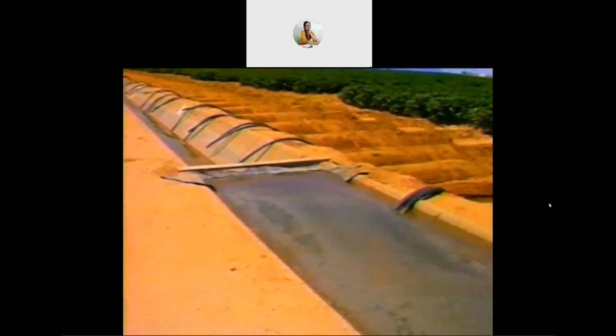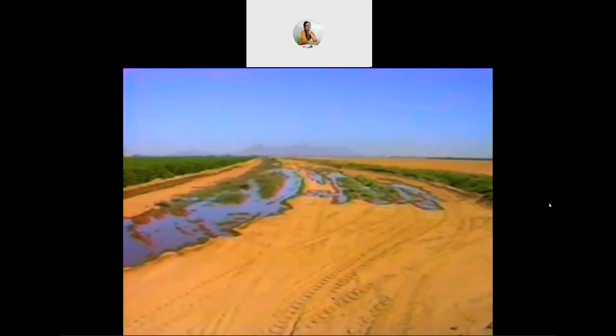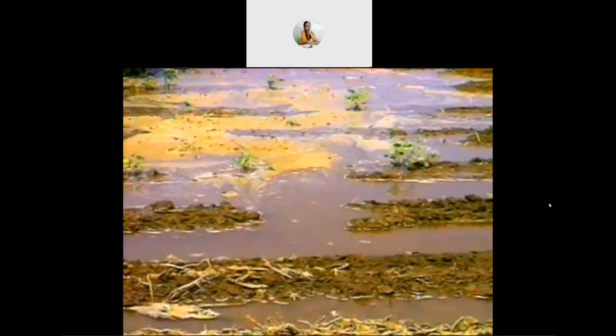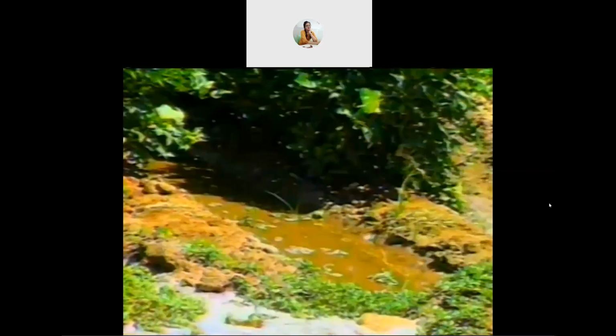When irrigating a field with blocked ends, we take the water off of the row sooner than if the ends are open. This means we applied less water. Water that would have run off the end of the field is now used to irrigate the far end of the field. We still have some deep percolation, but no runoff, and we used less water.